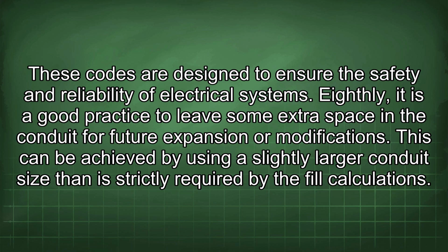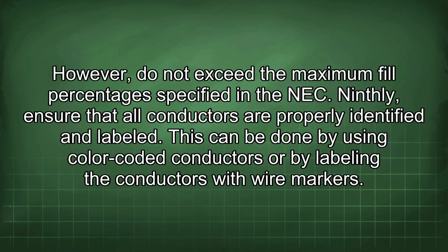Eighthly, it is a good practice to leave some extra space in the conduit for future expansion or modifications. This can be achieved by using a slightly larger conduit size than is strictly required by the fill calculations. However, do not exceed the maximum fill percentages specified in the NEC.